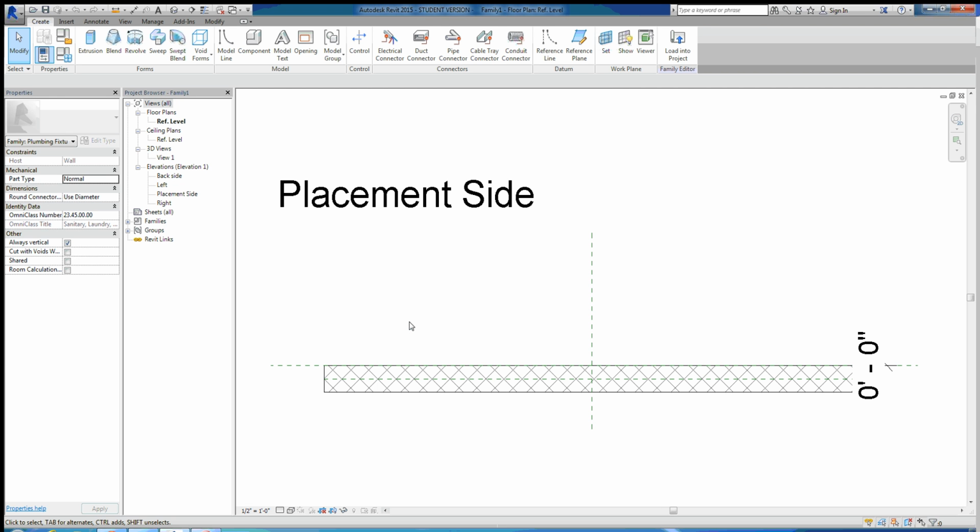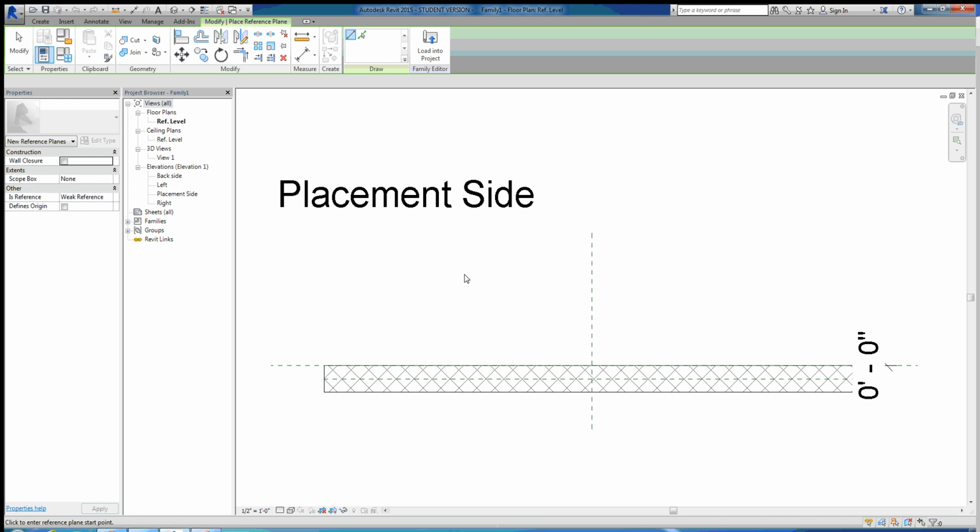You guys can pull up the cut sheet of the water fountains to get the dimensions necessary. We simplified them a little bit, so we're just going to make it so that the water fountain comes 18 inches out from the front and then is 12 inches wide. If you remember, it really doesn't matter where you draw these reference planes and what their dimensions are currently, because then we'll be able to come back afterwards and change these values.